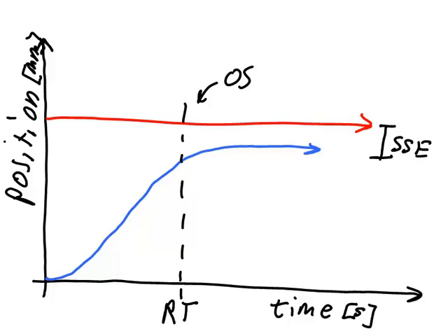In our tuning process, our next step is to slowly increase the value of Kp to speed up the response, reduce the steady state error, and, unfortunately, probably increase the overshoot.